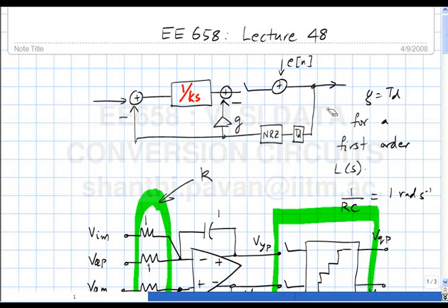Clearly the loop filter is the wrong loop filter when the RC time constants are no longer what you thought they were, which is why we are interested in figuring out what happens to the modulator. If you shake the table and the noise transfer function changes and the whole loop becomes unstable, then this is not a viable technique. So you are interested in figuring out how much the RC time constants can change before the loop becomes unstable. Does it make sense?